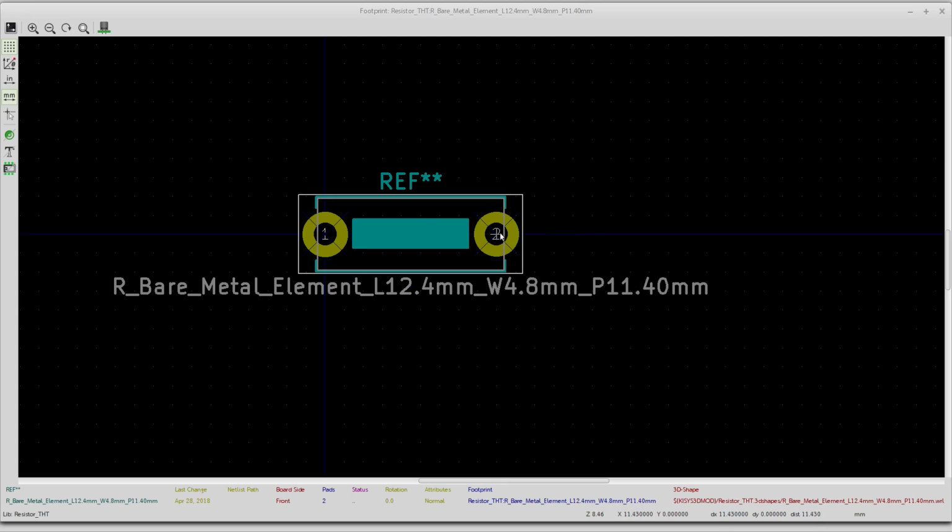if you hover over anything here, look down here in this corner, and you'll see these values, x and y, dx, dy. Now if I come over here, let's say to this dot, look right here at the dx, dy section. And if I hit the space bar, you see everything just went to 0. Now I can move this around, and it gives me a way I can measure things if I want to.